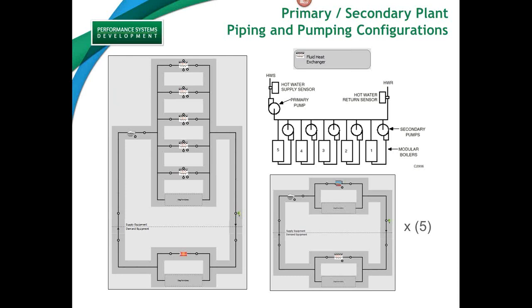I've put the link here. And by the way, this webinar will be recorded, and so these slides will be available on our website in a day or two. So if one would follow that link, they can download the OS analysis spreadsheet. And this spreadsheet is really meant to be an example of an alternative interface for the parametric analysis tool. It's meant to be an alternative interface running PAT on the cloud. So it really is meant to drive OpenStudio analysis through the Amazon EC2 cloud using high-performance computing resources.